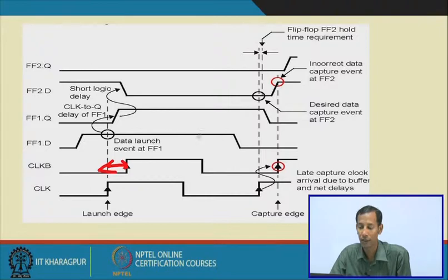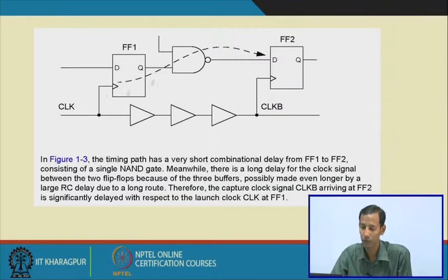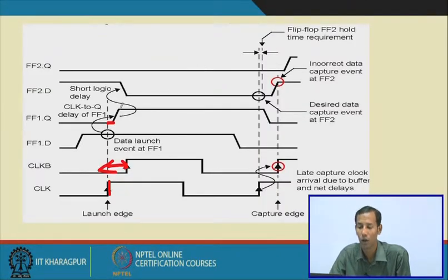So flip flop 1, this is the input data, the same data. Now at this particular edge, after some time this is the flip flop 1 Q, that means the output from the flip flop Q. That is very much okay. As this one is the NAND gate, the delay will be very much shorter. You see, only this much delay occurs based on the corresponding NAND gate.